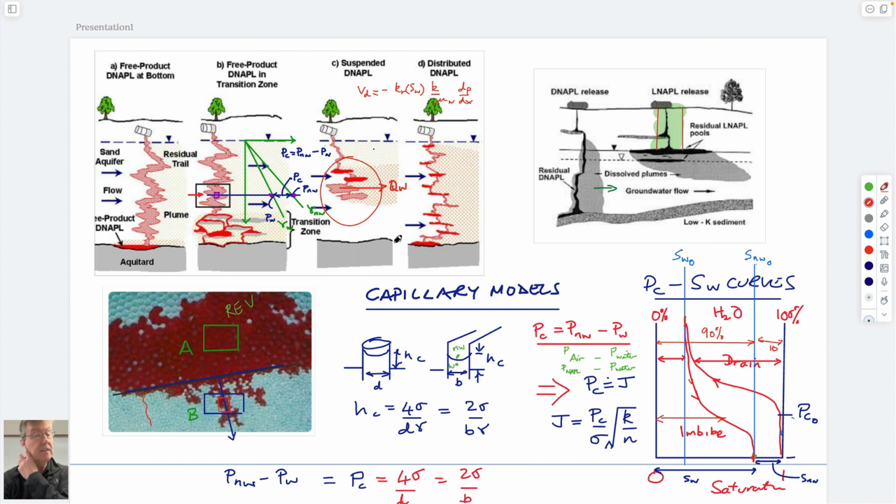And we've probably answered at least some of those questions. The reason it stops is because of a capillary barrier. The capillary barrier really has nothing to do with permeability, but permeability is related to the size of the capillaries, and it's really the size of the capillaries that controls what's going on. We can understand a bit about that by looking at the behavior of individual capillaries, either for porous media as tubes, as you'd think in this bead pack situation, where you have large grains, large pore throats, small pore throats, and that's the reason for this kind of structure.